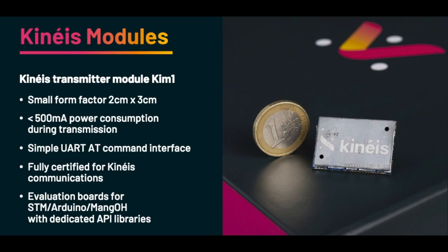The module is a higher level integration, 2 cm by 3 cm, with 500 milliamp power consumption during transmission. It can be interfaced through standard AT commands, and it's fully certified by Kinéis to communicate with our system. It comes on different boards: Arduino, STM32 or Mongoose boards that are pretty easy to use for development.